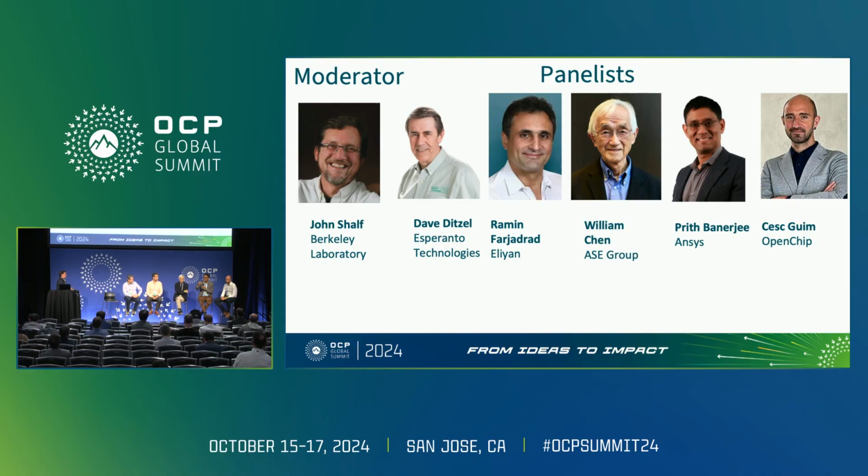So essentially there are IEEE standards, and each of these companies, Cadence, Synopsys, et cetera, are creating IP blocks as SoC blocks to be used today with the same technology, right? And so this is a homogeneous thing, all on TSMC's 2 nanometer technology. But it is possible to use that same chiplet idea, and both Synopsys and Cadence have UCIe-based workflows that will allow you to do this.